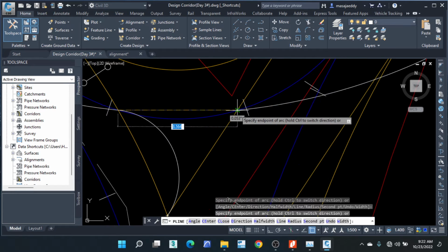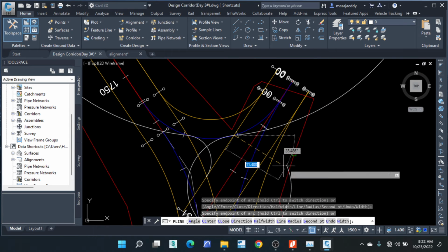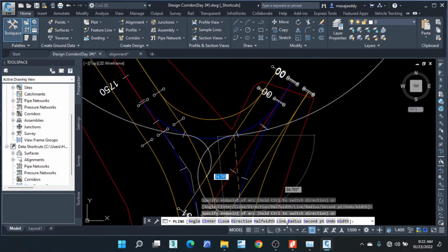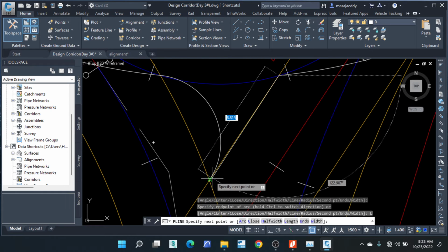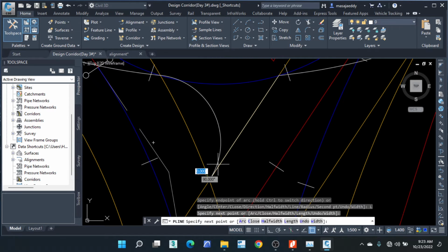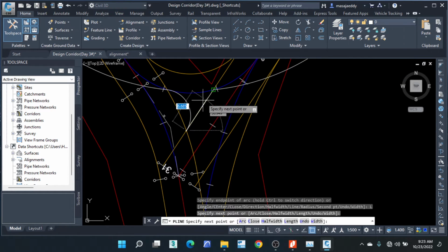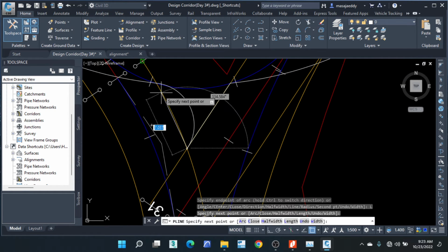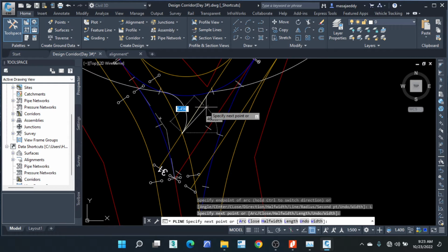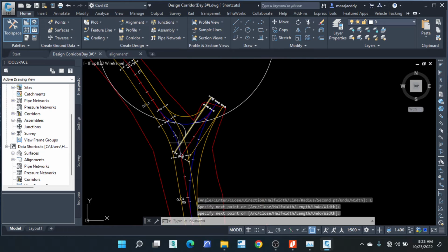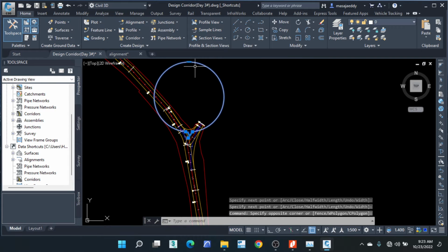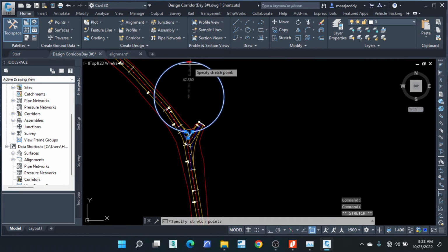So I'm done. I'm going to still use arc. Come and connect this area. As I'm done, I'm going to now come back and choose a line. Select a line, come and choose this area. These points whereby this is intersecting, they are all intersecting on the offset alignments. So you have this alignment. Remember we did one of the offset alignments, right? So let me first complete the polygon, then I explain a bit later.